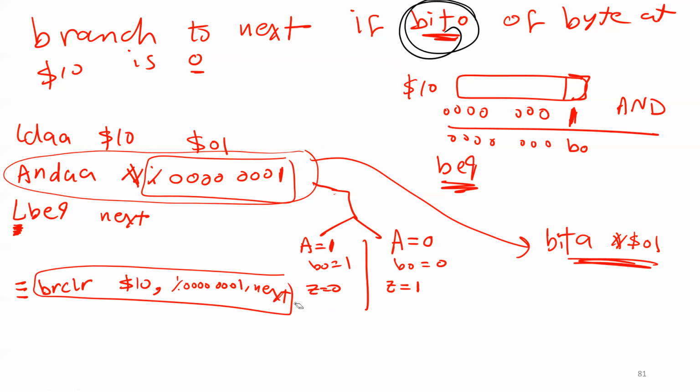It's easy. The other way, here I'm going to do AND, logic AND, as I told you. So in order to do logic AND, I have to write 3 instructions. Look at how I'm going to do it. Number 1, as you see here, guys, I'm going to read the byte at location number 10 and put it in register A. Then I have to use logic AND, because I told you, if you want to check some bits, the only thing you can use is logic AND. I did that because I don't have one instruction to do AND between a memory location and an immediate number. We don't have this one. That's why I have to put it in register A first.